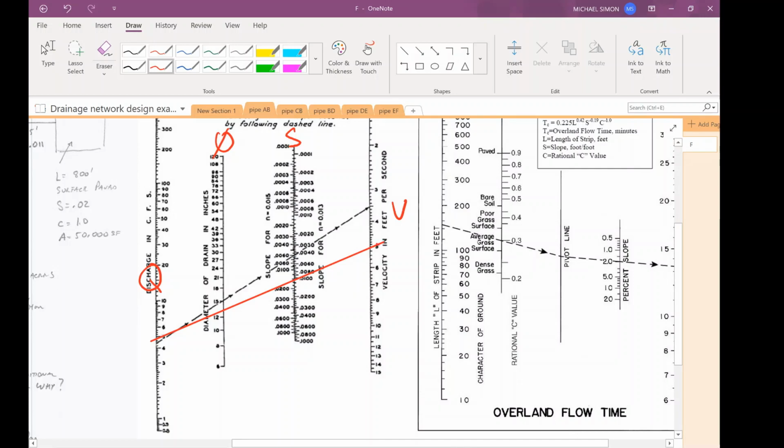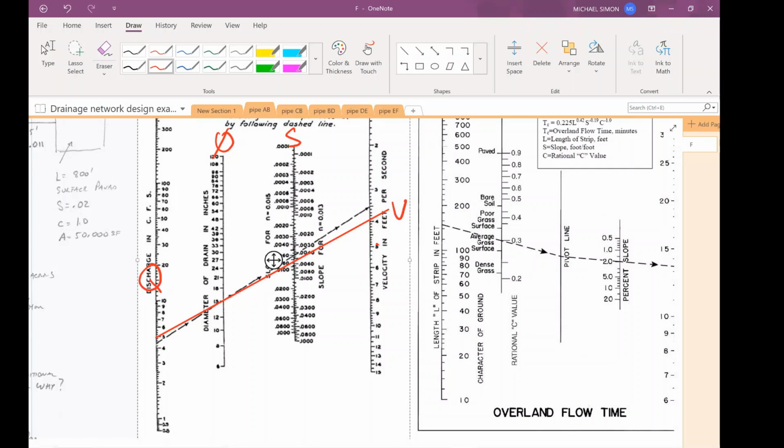Let's look at first, if we change the Q to, keep the velocity, try it again, keep the diameter at 15, and we move the velocity down, we can still maintain the same Q coming in. There we go. So 5 cubic feet per second going into the pipe. It would flow through a 15-inch diameter pipe. That would give us a 4 foot per second speed. The other option, and this is the option we're going to actually use on this design, I'll do this one in green. Now I want to draw a line.